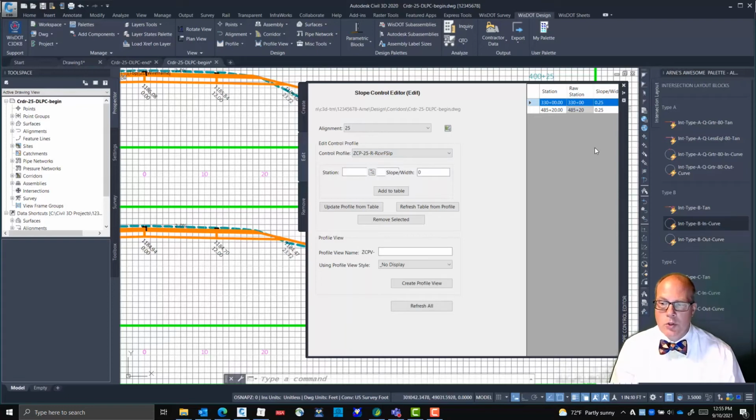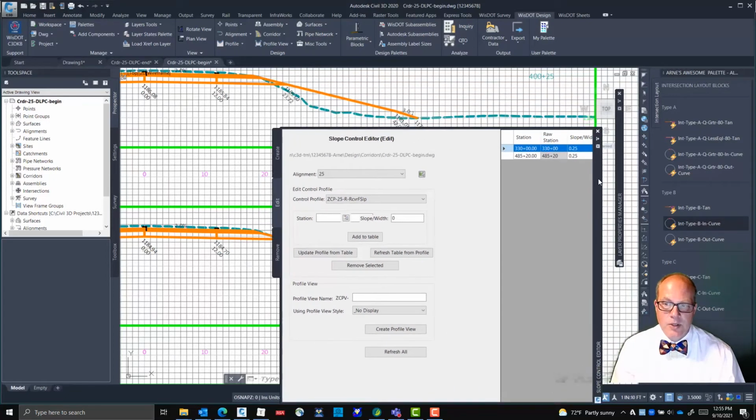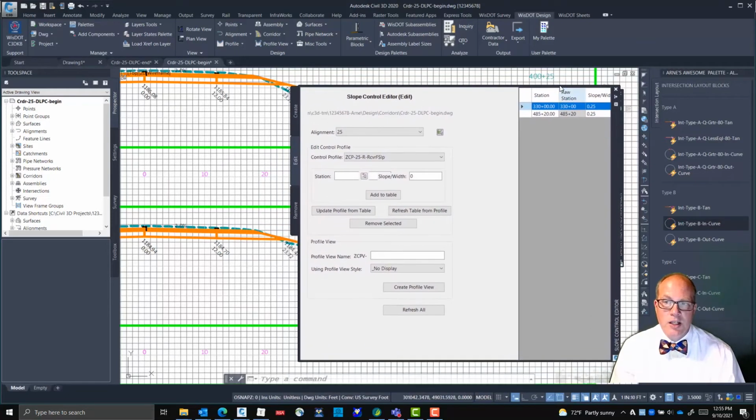What I'm going to do is bring that default value, that 0.25, to either side of station 400 and then change station 400. That'll keep all the rest of my station values intact and just change this one, turning it into a linear transition between those. So I'm going to throw in a station 399.75, and that's going to be 0.25.